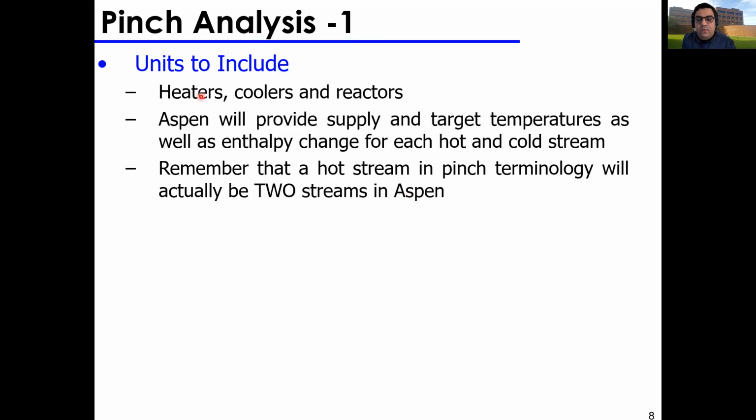And usually in your base case, you don't have heat exchangers, you just have heaters and coolers, right? You're just heating and cooling using utilities. You don't have a true heat exchanger which has integration of different streams at different stages. However, once you do your pinch analysis, you can understand at what points I can include a heat exchanger, where I can maybe use the hot products from a reactor to heat up the feed, or use the hot products from a reactor to heat up the reboiler in the distillation column, or use the hot products in a reactor to generate some steam to run a plant, or whatever it is.